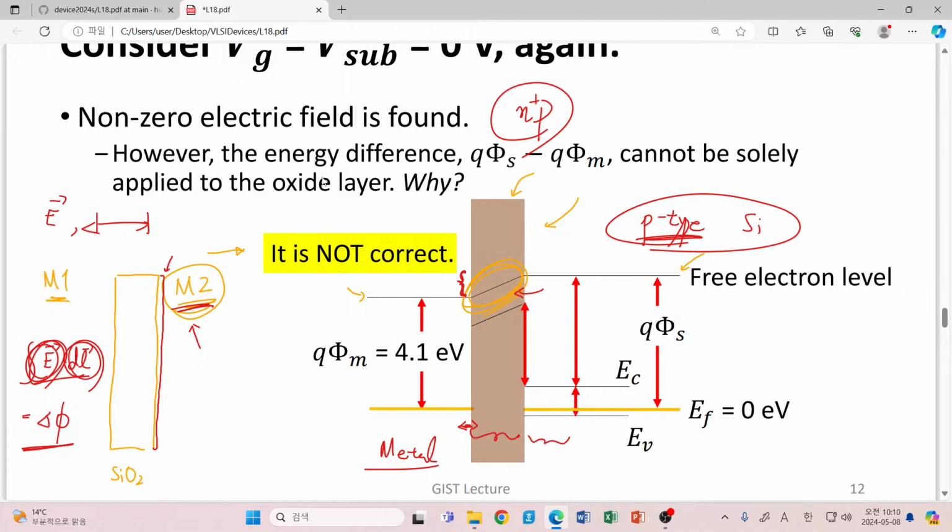So previously, when we used a polysilicon gate, and here we have oxide and silicon, of course this gate silicon is much more highly doped than this substrate silicon, but anyway, we had a certain amount of voltage drop in this part and the majority of the voltage drop between this oxide layer and substrate layer. That was the situation we had.